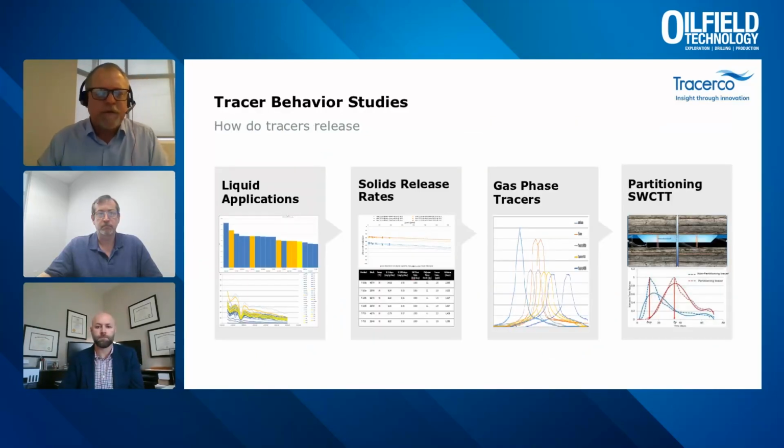When we speak about tracer behavior, we're talking about if the desire is to follow the liquid oil produced phase out of the formation, the tracers need to only be produced under those conditions, not in the gas phase or with the produced water, for example. Those tracers need to behave the same. The characteristics are really, really important in what the data is going to provide.